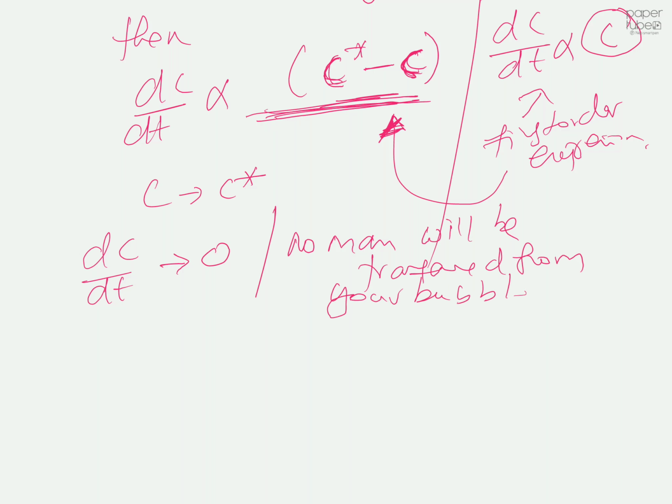from your bubble to the liquid. I'm giving this expression without explaining any theory, because for this module it's not really necessary. All you need to know is why there is diffusion, what's meant by diffusion, and how you transfer oxygen from the bubble to the liquid. Once you supply oxygen, your gas molecules which are trapped in the oxygen bubble are going to diffuse into the liquid.